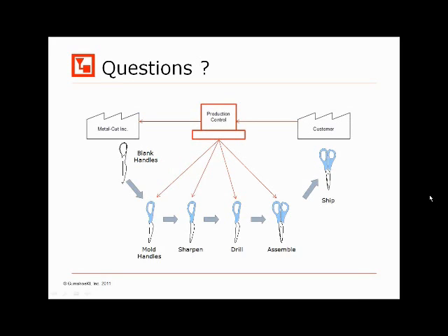How often should the VSM be updated? That's a good question. One of the great risks for VSMs, and I've seen a lot of those, is they end up as this kind of wallpaper. By making it electronic, by doing the calculations, by visualizing it, by getting people engaged, hopefully there's less of a chance of that. A lot of people update it every month. It's certainly not something that's updated every day. Having said that, we have one client who actually has the value stream map on a smartboard throughout the facility, and it gets updated daily. They have gadgets tying into inventory amounts, key metrics on the map, so that everyone is aware of what's happening on the value stream. That's a little unusual, but perhaps with the electronic age, we'll go more and more that way.